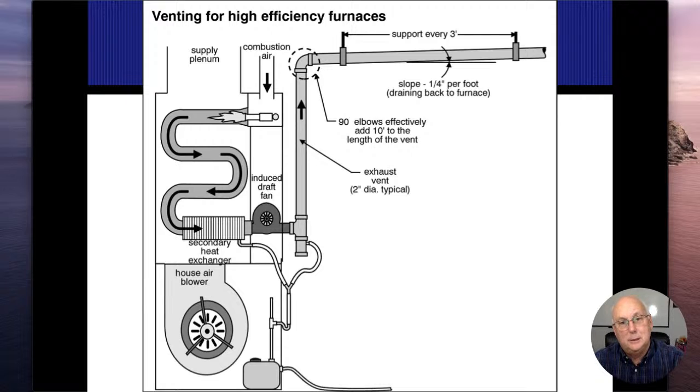Those PVC pipes, first of all, they're designed to take the corrosion. The fans are usually powerful enough to go ahead and push all the air out. And then they are sloped backwards, not just to let the heat rise, mind you, but more so to let the condensation fall back. And then we end up collecting that condensation and we have to allow it to drain.